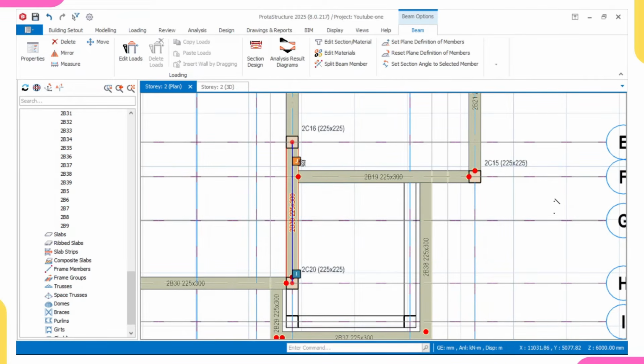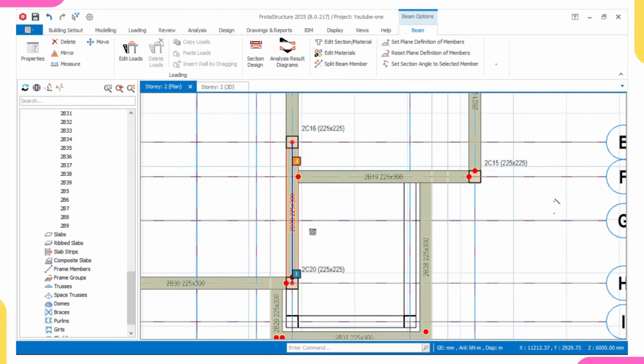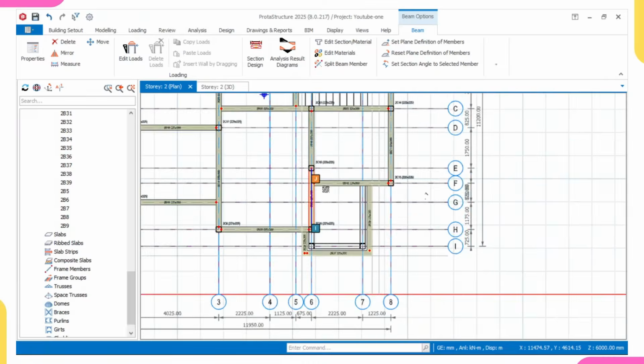But no, if you do it like that, I don't think this beam will be the one carrying this. So I want this to be a straight beam, so that it is carrying this secondary beam. That's why I say they should not split it for me, so that this will run from here to here and this will carry this. Because if they split it, that means this beam is no longer carrying this. Do you understand? Yes, this is the ideology. So you have to understand what you are modeling and what you are doing.